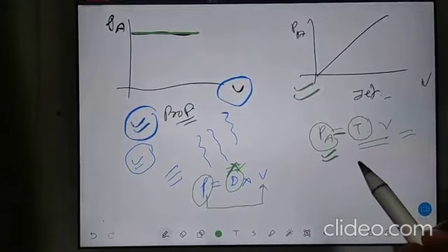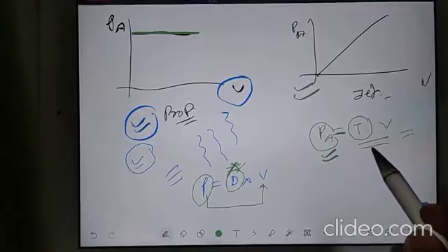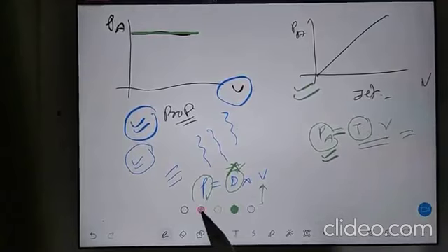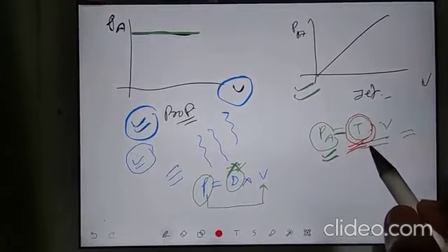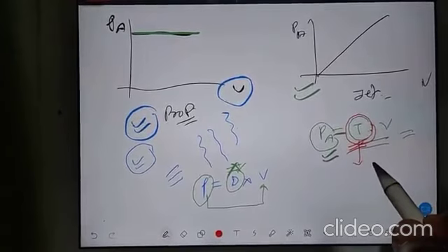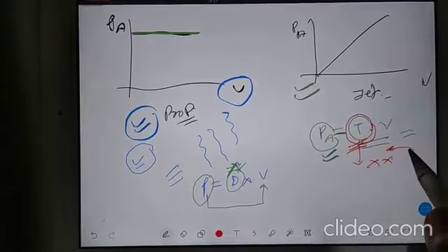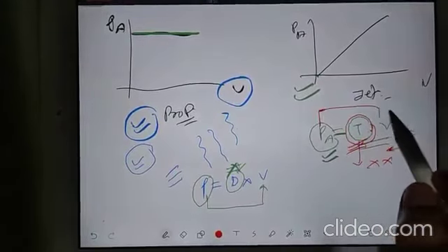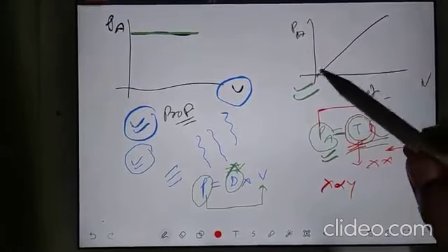Because your thrust available is constant. Thrust available is constant in case of jet engine. So power is directly proportional to velocity. So you got x proportional y, that's why it is increasing.